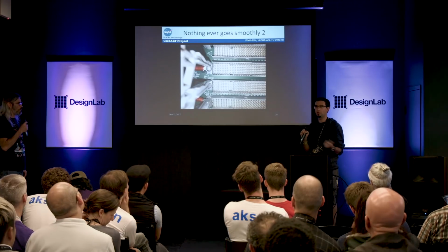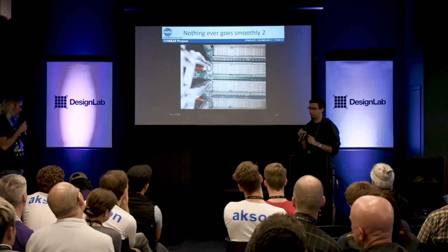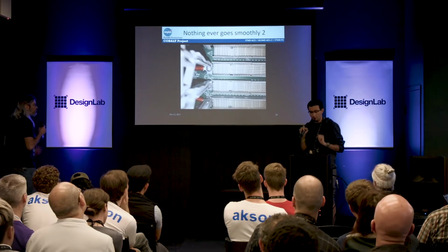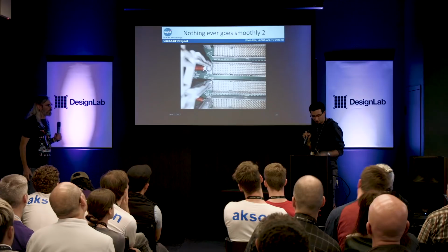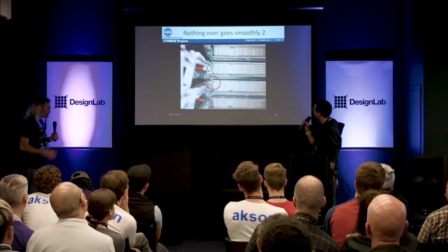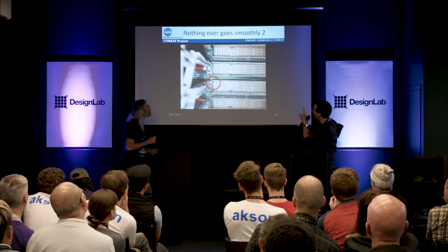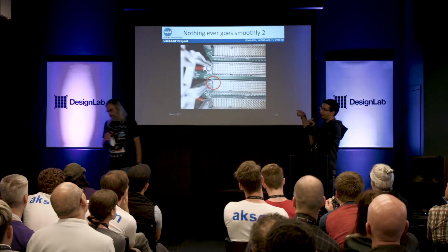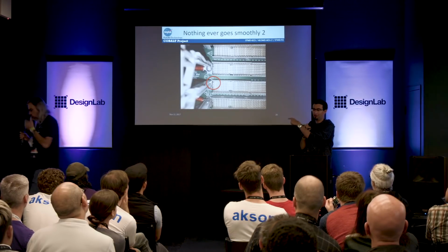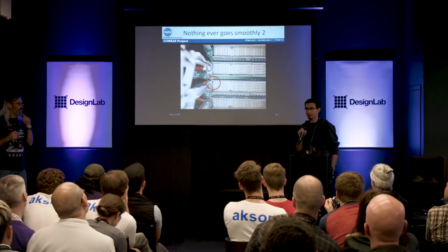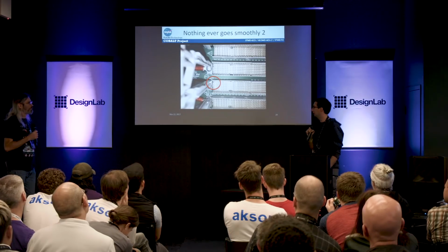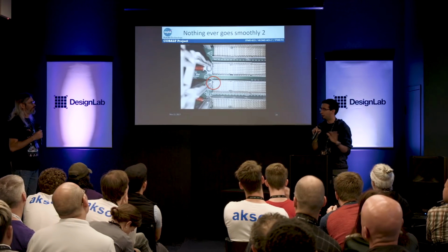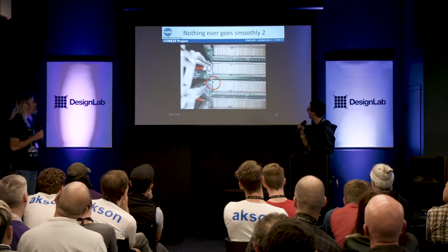I'm like, what the heck could be the problem? We checked it out, buzzed a few things out. We're like, I can't figure this out. Pulled the card out and then looked at the pins. We're like, what could it possibly be? This stupid one single pin bent and shorted against VIO, which is our voltage for the logic. And so the logic rail was faulting, and thankfully it didn't cook any hardware, but I hate you, CPCI.